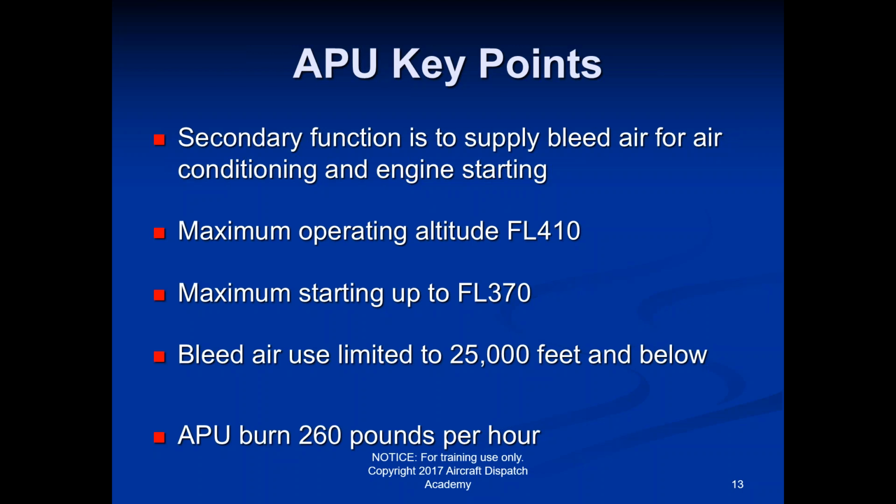And they can fire it up from the cockpit, and they turn it on, and it starts to suck in air. There's this little door that opens and flips down, and it allows air to come into the APU and for it to draw air in, and then it spits the air usually out the back. In the 700, the exhaust comes out of the tail cone. On the 200, the exhaust comes out of the side of the aircraft.